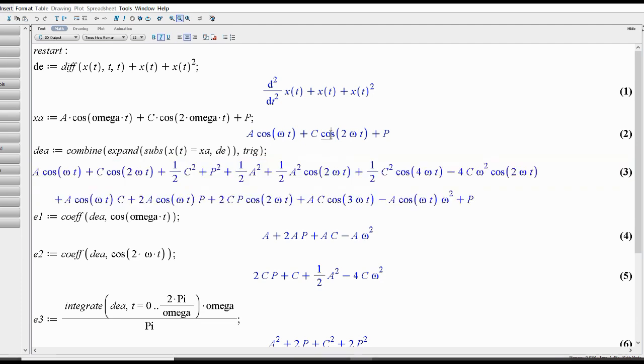In the harmonic balance, you see constant and cosines are there. Over here also these are constants and cosines. Some cos 3 omega t has come, and 4 omega t has come, but we will not worry about those. We have to balance the constant, the cos omega t, and the cos 2 omega t.